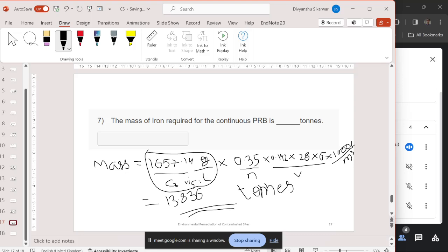So here, grams per liter, where liter represents the volume, basically the volume of water present in the pores. Water will occupy the pores only, and that pore volume is calculated through the porosity: if we multiply it with the total volume, then we will get the volume of pores. So in this calculation, grams per liter, and this complete thing is the volume calculation of the pore.